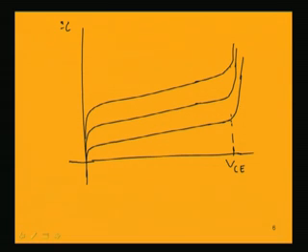curves. That means the characteristic curves will crowd around this VCE maximum, which is also called VCE sustain. That means this much voltage is required for sustaining that breakdown, because for all the collector current characteristic curves for different base currents that we are showing, near breakdown they all will be crowding around the same value of VCE, that is called the VCE sustain. So, that voltage is the maximum voltage or rated maximum for a power BJT.